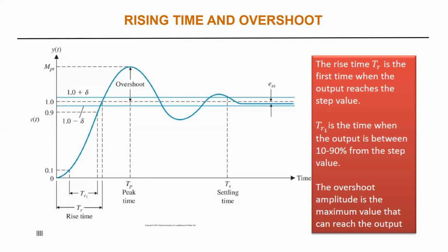So we are going to relate the maximum value of the response due to a step, and when that will happen. We will look into also the settling time, how fast the response will go. We also, as a measure of the speed of the response, will take the rise time, which is basically going between 0.1 and 0.9.